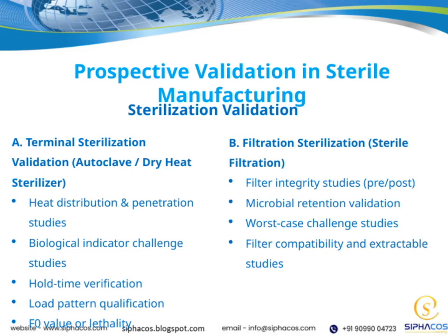Now, let's discuss sterilization validation, starting with filtration sterilization, also known as sterile filtration. This involves conducting filter integrity studies both before and after the filtration process to ensure the filter is functioning correctly. We also perform microbial retention validation to confirm that the filter effectively removes microorganisms, which is critical for product safety. Additionally, worst-case challenge studies are carried out to test the filter's performance under the most challenging conditions, ensuring robustness. We also evaluate filter compatibility and extractable studies to verify that the filter materials do not leach harmful substances into